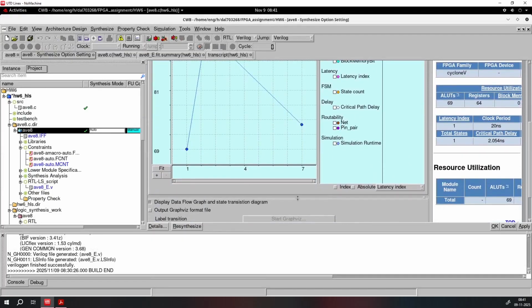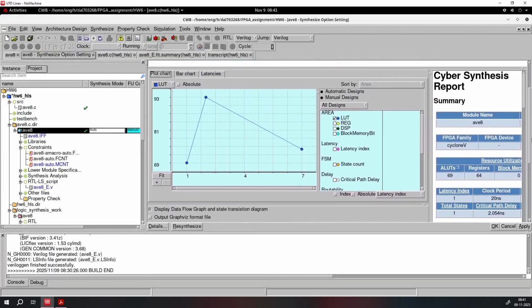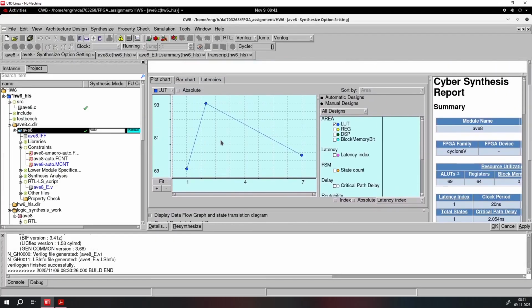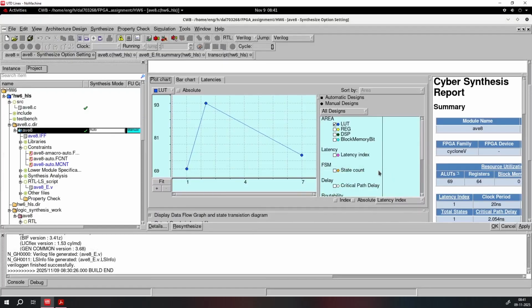It has a cumulative view of all the design syntheses that we performed during the cycle. Here I have maintained three designs for evaluation. The first design is the auto-generated design, where the only modification I've made is to the functional units. The first design point consists of four 8-bit adders and three 12-bit adders.